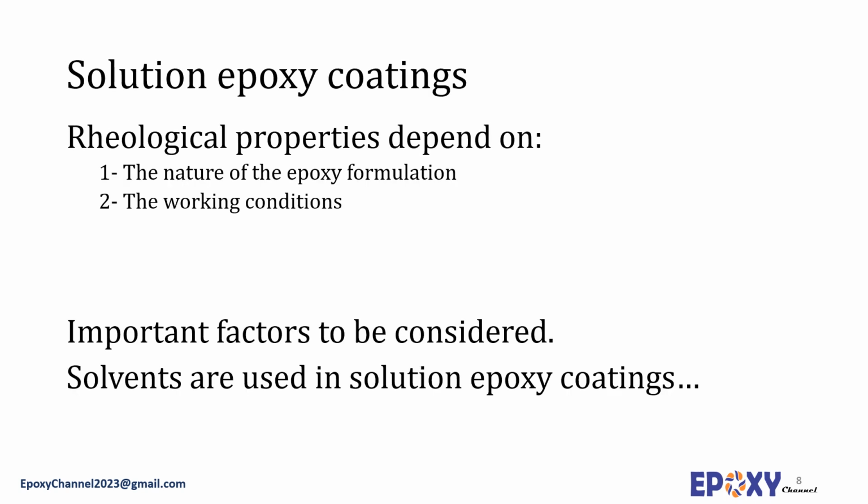In this system, the rheological properties of the epoxy formulation have been amended by employing solvent systems to adapt it for specific applications. Primarily, the rheological properties of epoxy coatings depend on the nature of the epoxy formulation, for example, its epoxy type, molecular weight, fillers, pigments, additives, solvents, etc., as well as the working conditions, for example, the applying temperature.